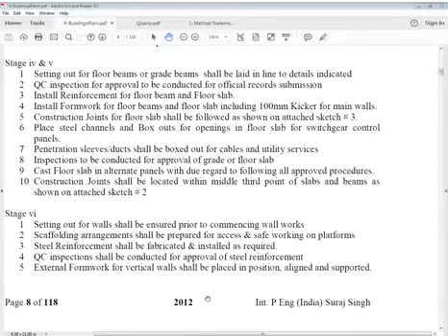Now, place steel channels and box outs for opening in floor slabs. It means if it is designed, there will be many box outs or block outs, you can say, in switch gear control panels. There will be many box outs or channels, plate steel according to your design, because this is an industrial building, or an electrical building in industrial projects. So place steel channels and box outs for opening in floor slabs for switch gear control panels. You know what I mean, switch gear, don't be confused.